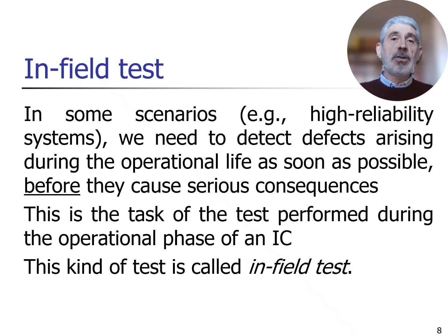So this kind of test, which is performed while the circuit is already in the operational phase, while the circuit is already mounted on a board which operates inside a system, is called in-field test.